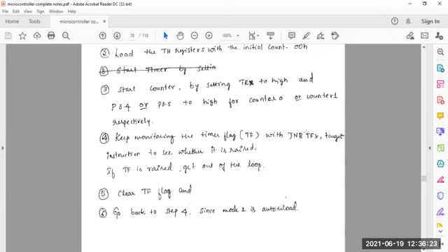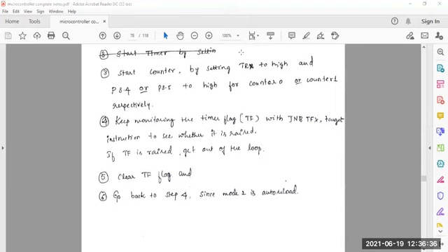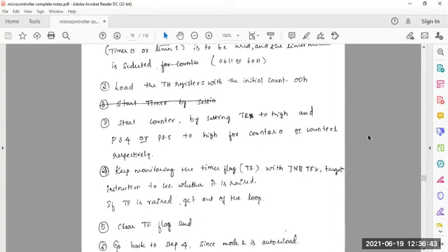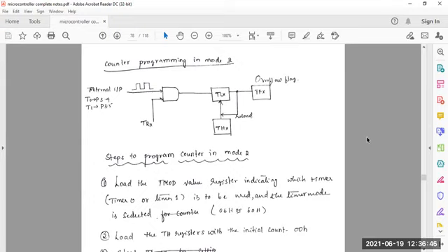And then once the TF flag is raised, that is nothing but once the TF value becomes 1, you have to clear the TF flag and you have to clear the TR0 value or TR1 value. Okay, you have to clear. Again, auto reload the TH value. Okay, that is what we are going to do in the counters. I'll give one example in the Keil. Example program in the Keil for counting the values. I'll give some examples. Let me show that one.